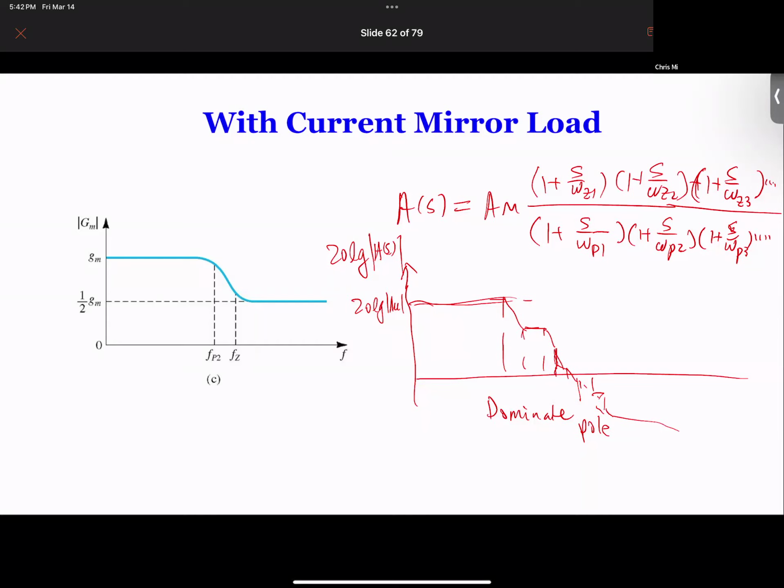some of these poles or zeros are going to start to play. I don't have a good analogy, but when you have feedback, you have to be careful. Some of this could come back to haunt you. A simple example: you know your signal is here, and you design your dominant pole here. But in your system, there's noise coming in at a certain frequency over this region. Normally you wouldn't care because that signal gets attenuated so much, right?